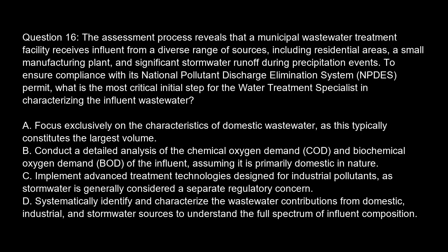Option A. Focus exclusively on the characteristics of domestic wastewater, as this typically constitutes the largest volume. Option B. Conduct a detailed analysis of the chemical oxygen demand (COD) and biochemical oxygen demand (BOD) of the influent, assuming it is primarily domestic in nature. Option C. Implement advanced treatment technologies designed for industrial pollutants, as stormwater is generally considered a separate regulatory concern. Option D. Systematically identify and characterize the wastewater contributions from domestic, industrial, and stormwater sources to understand the full spectrum of influent composition.